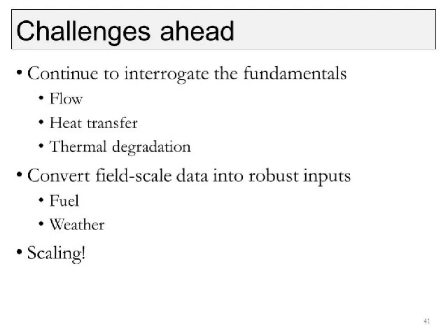For anybody familiar with FDS and WFDS, there are approaches to look at the fuel layer, particularly if you just have a litter layer like this, and treat it just as a boundary condition as opposed to directly resolving the thickness of the fuel and all the flow through it and everything that we're doing in the lab scale simulations. So can we reduce that and treat it more crudely? That might be one scaling method.